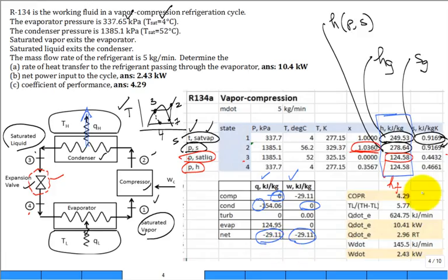And then you just calculate those quantities of interest. Notice the COP based on a Carnot cycle was 5.7. It's dropped. It's not going to be as efficient, not going to be as good. The coefficient of performance is lower. And I think the refrigeration tonnage is about the same, but you require more work. More work. Can you solve a problem like that? What do you think would be a change to that problem?